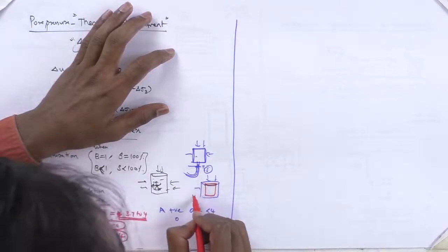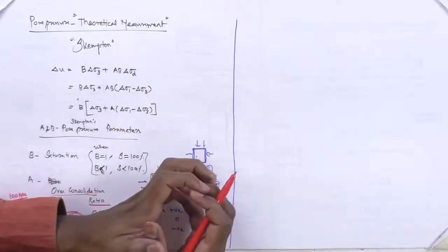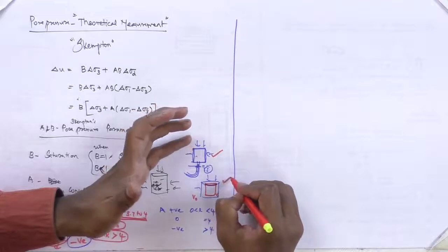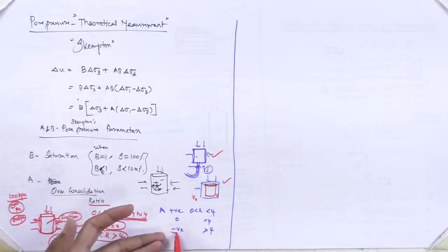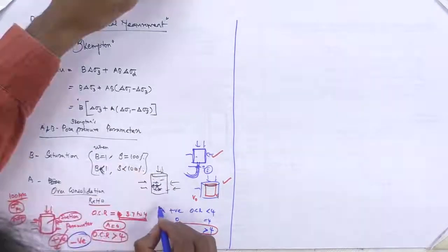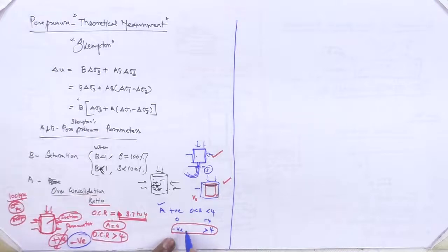So this is an initial volume V0, this is a final volume. So the volume is going to be compressed and fails. So here the case is different. So that is why there is a possibility of negative pore water pressure also. You should understand this. So fine, this is a negative pore water pressure.